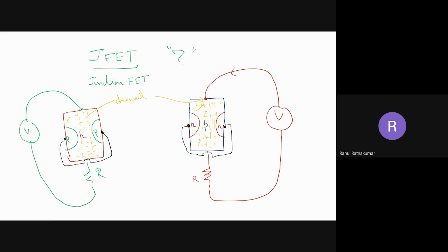This is only a PN junction analysis. Now what I'm going to do is control the current by changing the depletion region between the N and P type region. We know in a PN junction, in order to increase the depletion region, I need to have a reverse bias. That means P should be given the minus and N should be given the plus. So this is the depletion region, right? I'm trying to create a depletion region in these two cases.